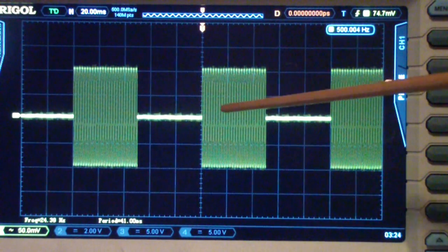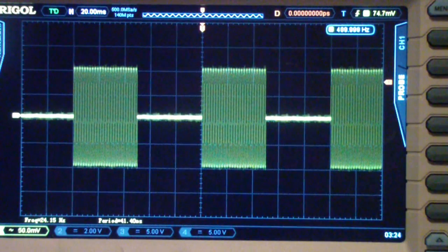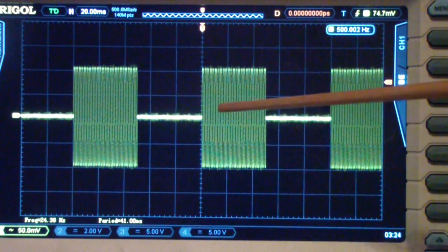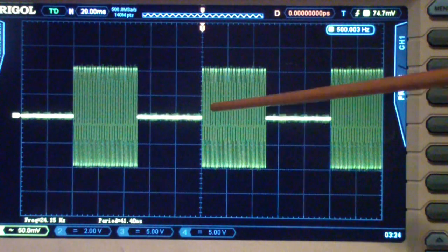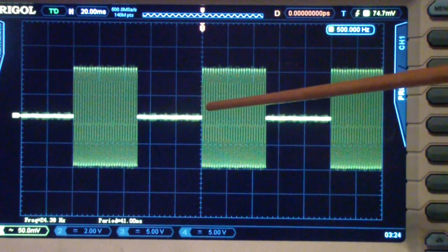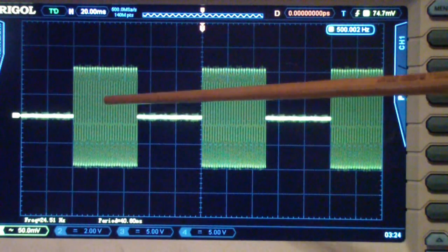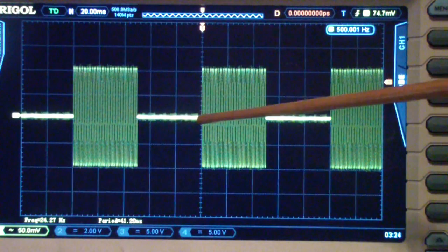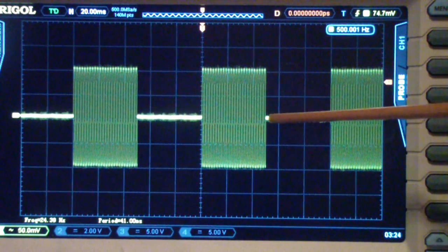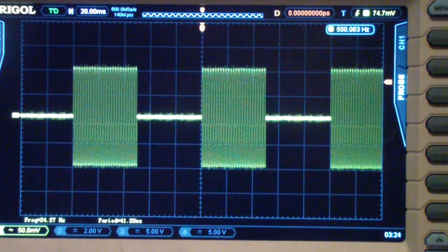One of the kinds of waveforms that you really need to use for the testing of amplifiers for music is some kind of a burst signal. Now that's what this is. This is a burst sine wave. The signal comes on, it's a sine wave for a period of time, and then the signal goes off. What we're trying to do here is simulate instruments like plucked guitars and things of that sort.